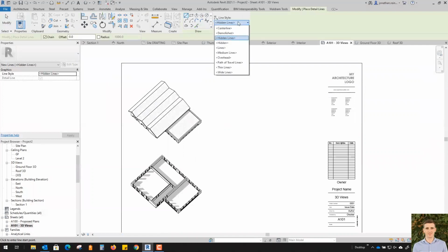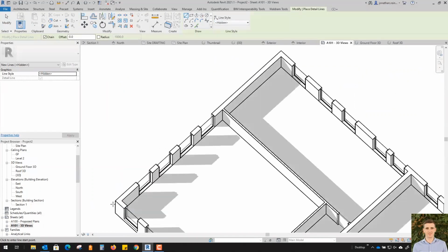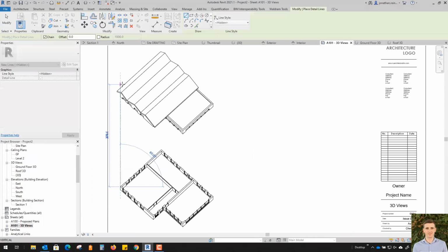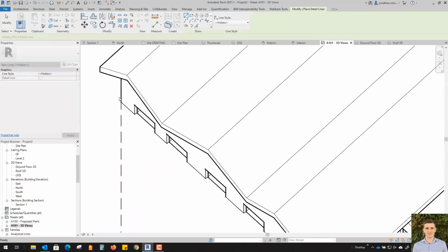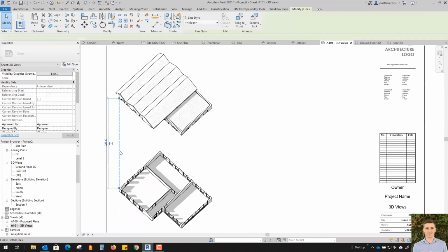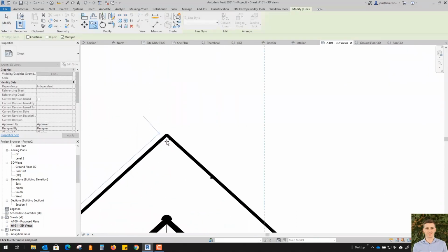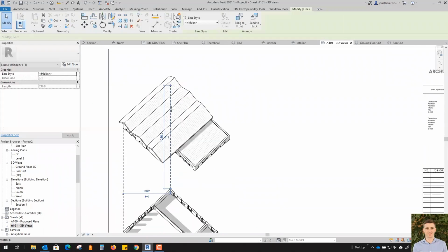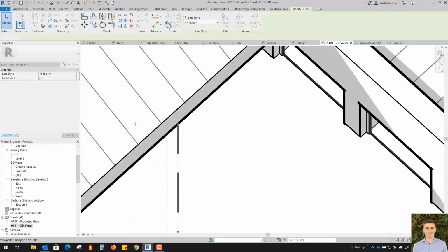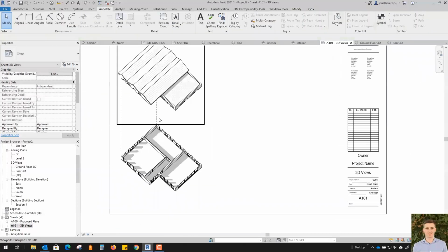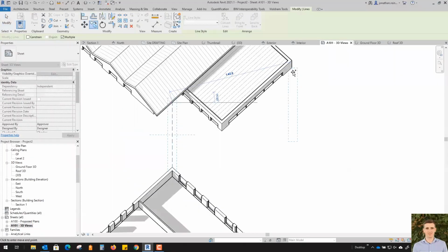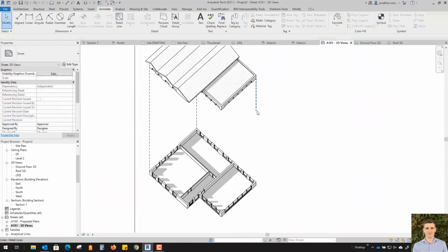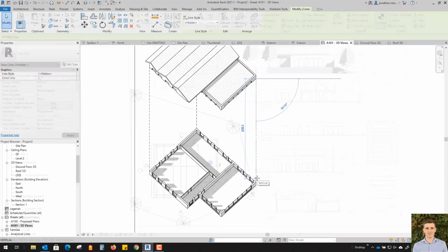To further enhance your drawing sheets, you can also add 2D lines on that particular sheet. For this example, where we've put the cut 3D floor plans, I'm going to add something called a detail line from your annotation tab, and this only exists on this particular sheet in this view. It just shows the extrusion of the roof over the floor plan. These are just basic 2D lines, nothing complex here whatsoever, just copying and replicating those 2D lines across from the different corners of your building. It just reads a bit better, depending on your preference or intention with the actual drawing.